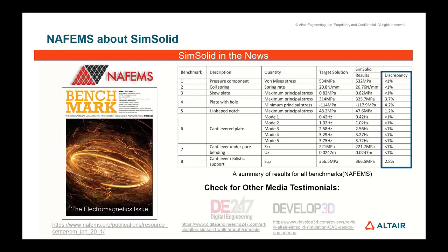Can environmental effects like rain, wind, etc. be simulated using SimSolid or Inspire? You can specify a transient temperature in all of the cases, but in terms of rain and wind, etc., you might want to start using probably FSI, so fluid structure interaction, for that. Although I'd say in any sort of simulation world, unless you're looking at agricultural, that's a bit of an overkill. You just need to make a few assumptions for most of your simulations.